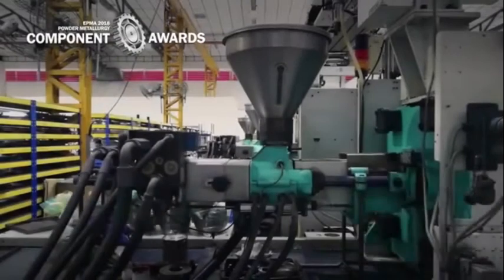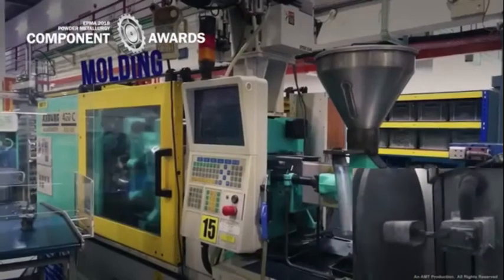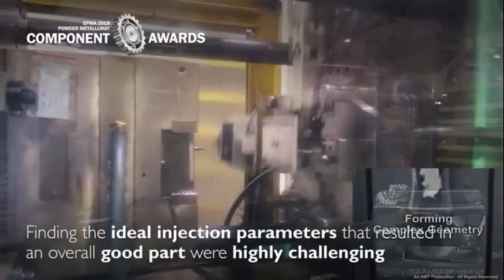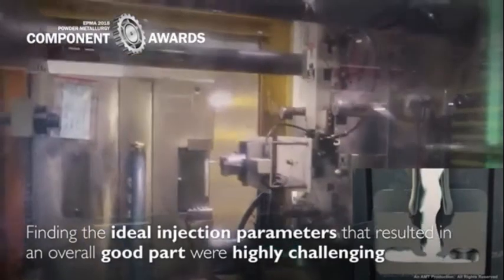On the contrary, it is necessary to maintain high packing pressure in the inner core channel, as any loss in pressure will encourage weakness, resulting in cracks. Finding the ideal injection parameters that resulted in an overall good part was highly challenging during the development phase.